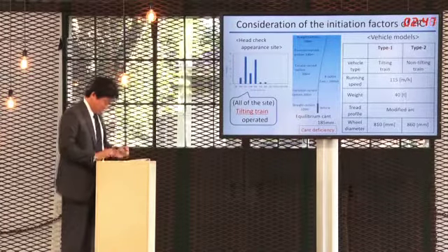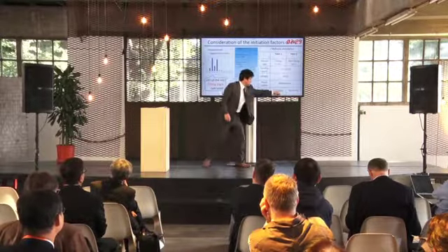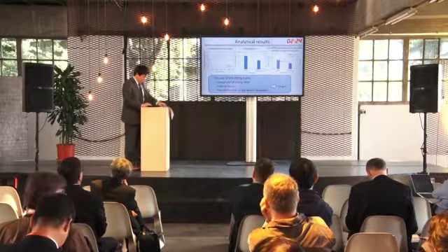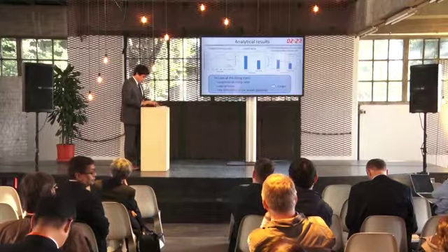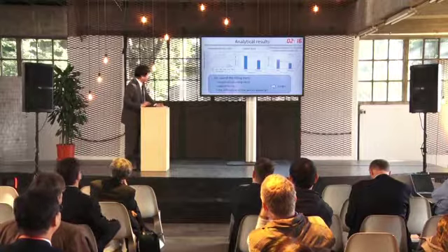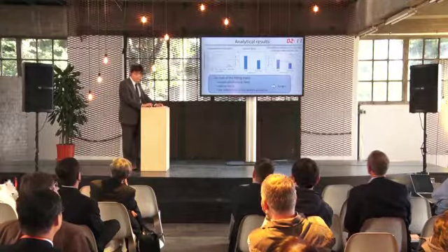Here shows the details of the vehicle model on the slide. These parameters are based on the actual vehicles in service, especially the values of the wheel diameters, which are different. Here shows the analytical results of the longitudinal creep ratio, the lateral force, and the difference between the diameters at high and low rails.